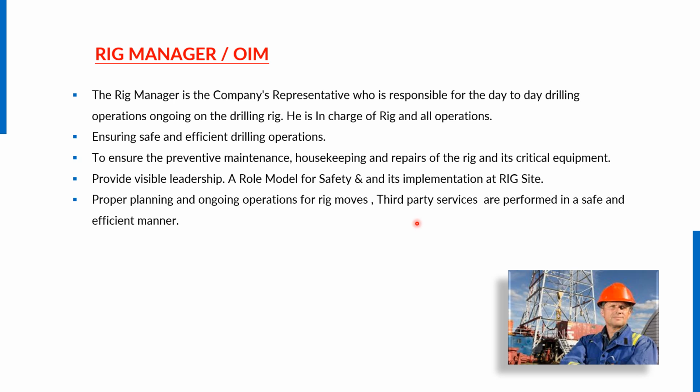He has to gather all the important documentation which has to be furnished by the rig contractor to the client at the time of the rig move. For example, those can be the critical load data sheet. There should be the JSA for all the operations, and he has to ensure that all the equipment used at the rig move has its daily inspection checklist. If it is a crane or forklift, the operators should have third party certification, and the crane should have the third party fitness certificate.